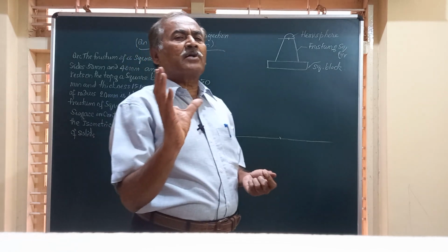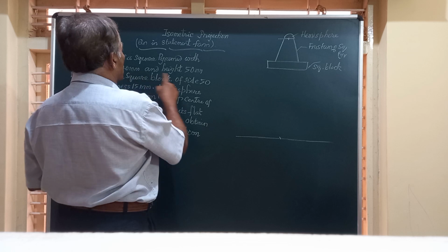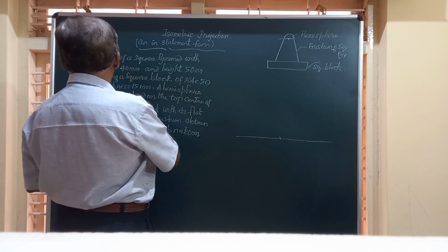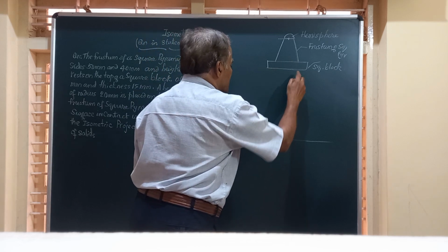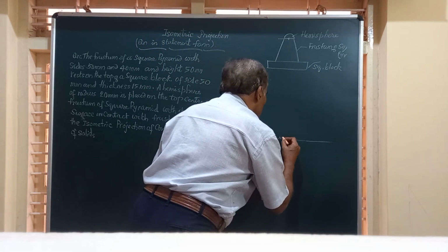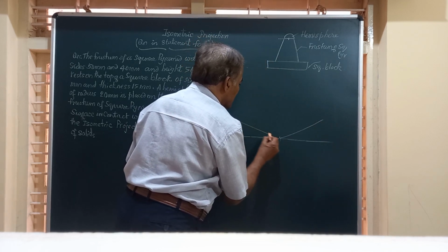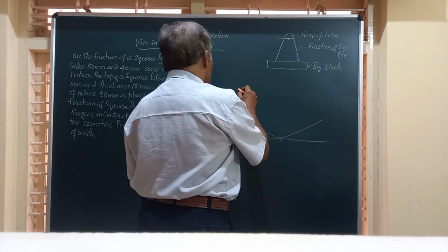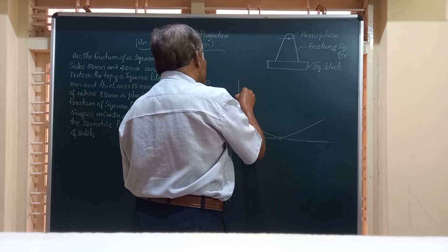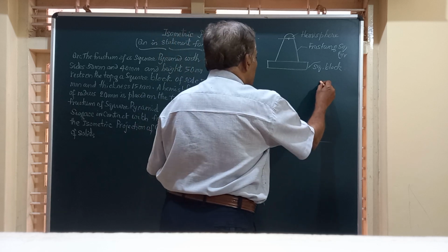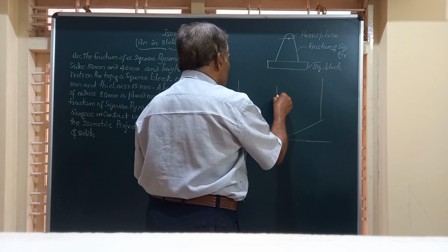That means it will have a square cross section and the thickness is equal to the given value, a square block of side 50 and thickness 15. So what I do, friends, I will start from this side. I am going to draw two lines at 30 degrees to each other. And from all these, I am going to draw vertical lines. Vertical line from here, vertical line from here, a line from here.